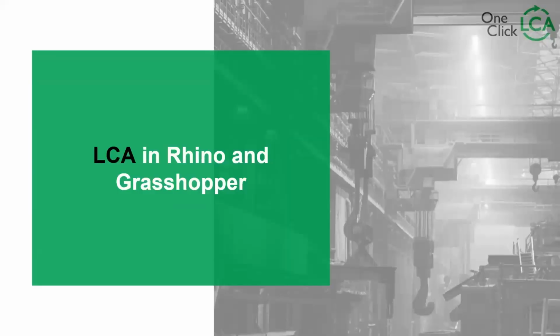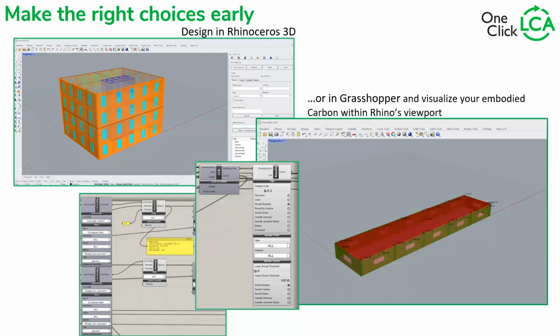Just to wrap this presentation up, I just want to bring up LCA within Rhino and Grasshopper using our integrations. We very recently published two integrations, one for Rhino, one for Grasshopper. The one for Rhino is fairly simple in the sense that all you need to do is draw the elements you want results for in their specific layers, assign materials to them, and then you'll be able to get results for the geometry that you drew.